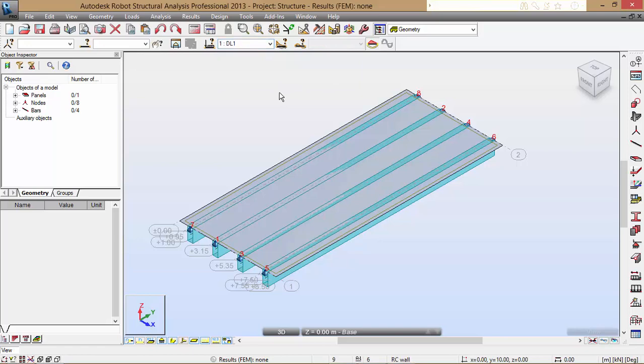So let's go to dead load 1. That should be the self weight. As you can see, it glows red, showing that our system is in place. Next, we are going to superimpose dead loads. For superimposed dead loads, we are going to start with a 60 millimeters thick asphalt overlay plus railing.